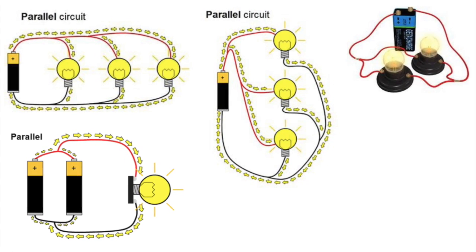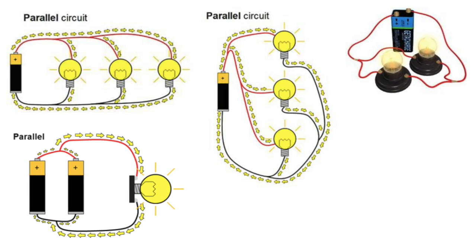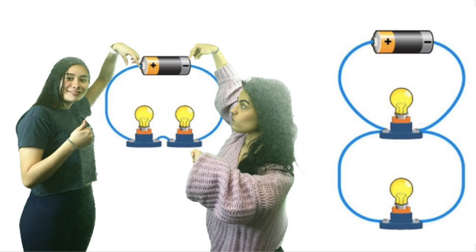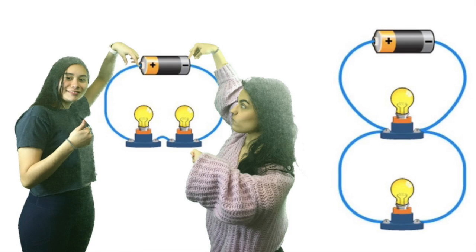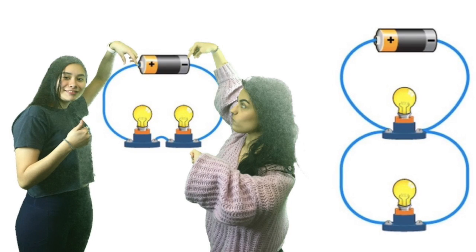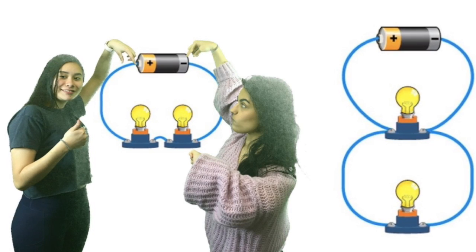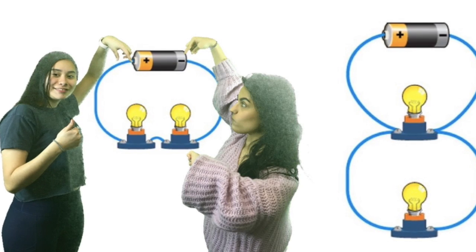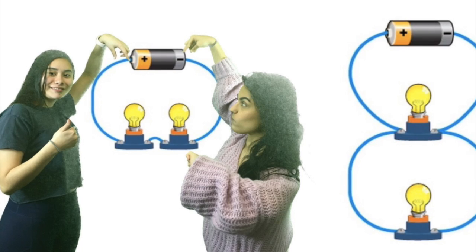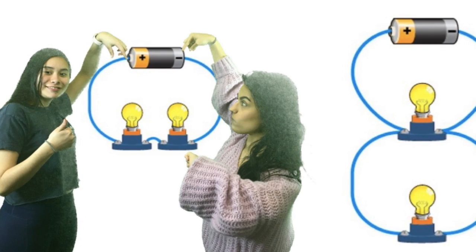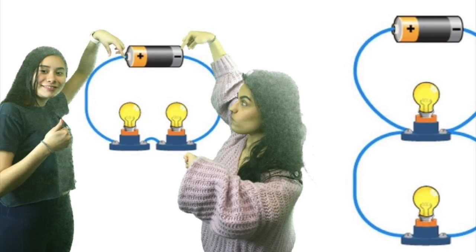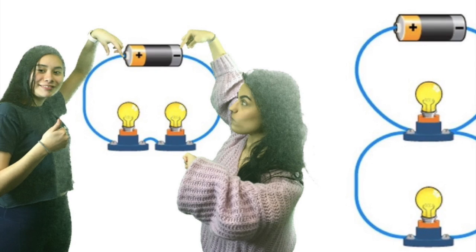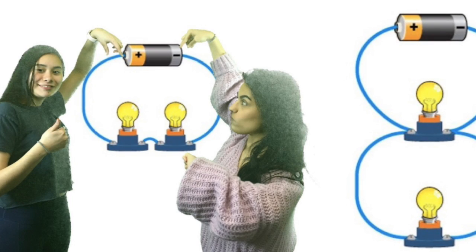While energy flows through the two types of circuits, the connections are just fundamentally different. A complete circuit is the only way current can flow, when there are no gaps. Electrons flow from the negative terminal on the power source through the connecting wires and components, such as bulbs in our example, and back to the positive terminal, completing the circuit. Negative to positive. If there is an opening stopping the flow of electrons, the circuit is no longer complete and there is no current to flow through.